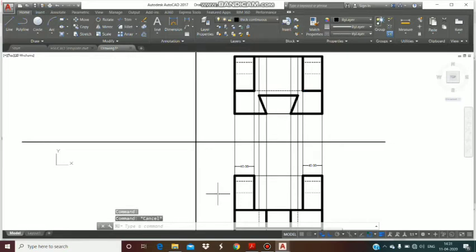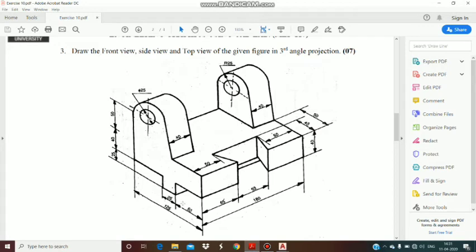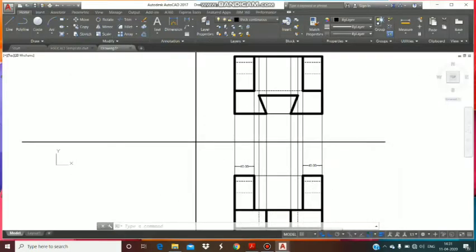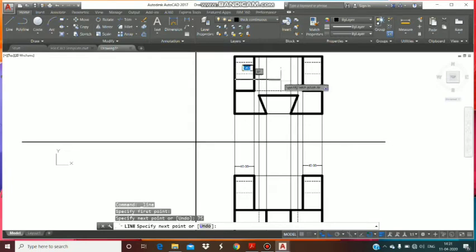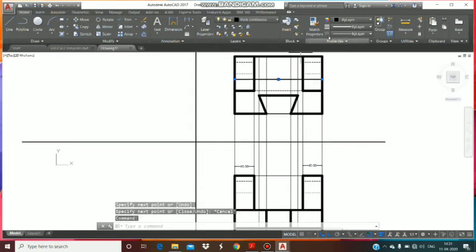Okay, there's another line at the distance of 75, because this 50 and 25, there's a block. This should be also hidden. At the distance of 75 from this block, draw horizontal line up to this one. This should be thin and hidden too. So this is top view.